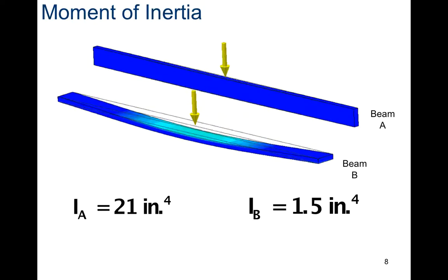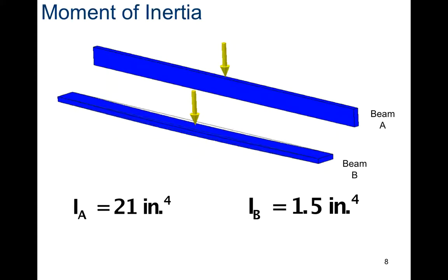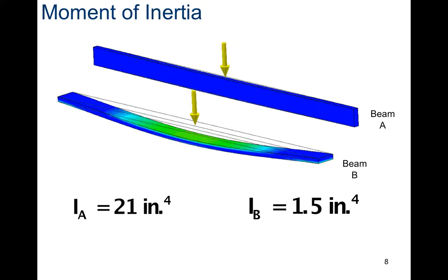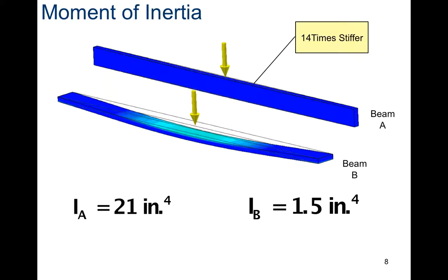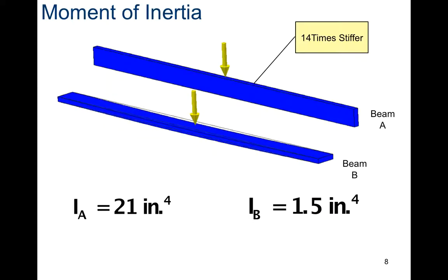Now, depending on how long that beam would be, it's a bit exaggerated, but not too much, and you guys will see when you start to stand on those beams. When you have a shorter beam, of course, you're not going to get as much deflection. The longer the beam is, the more deflection that you'll get, and that is actually another characteristic that's going to be important here. Okay, so beam A, when we have it joist, is actually 14 times stiffer than when we have it plank.